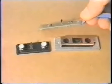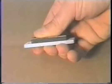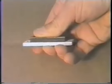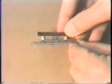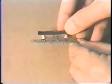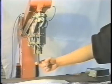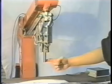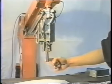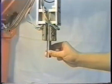On a printed circuit board are located the optocouplers and the other electronic components. If force is applied, elastic body deforms. Sensing elements measure its deformation in normal and tangential direction. Two optocouplers are mounted near the ends of the sensor, measuring the object inclination. One optocoupler, orthogonally mounted in the middle of the sensor, is sensitive to axial deformation. Using information from all sensors simultaneously, intensity and direction of external force can be determined. In this experiment, robot arm retreats, tending to eliminate the excess external force acting on the object.